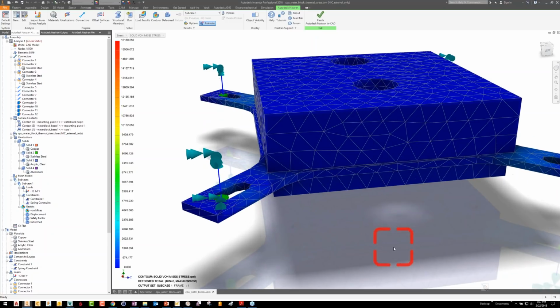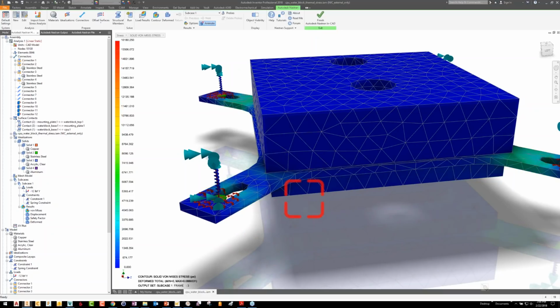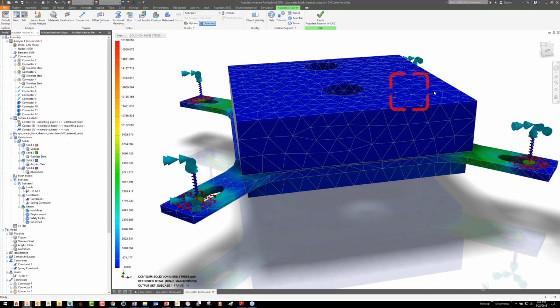As a result of that, though, this particular tab is not free to move as much as the others anymore. So the behavior is different, the stresses are different. I just need to be aware of that and accept that these guys are probably representative of what all 4 tabs are going to see, and this one not so much anymore.